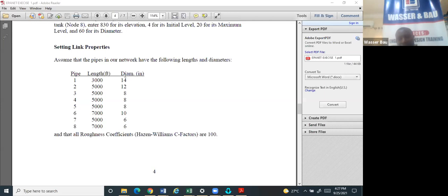All these things have to be designed anyway, depending on how many hours you are pumping and the capacity of the pump: the head and the discharge. Every pump is defined by 2 things, the head and the discharge. The higher the head, the lower the discharge. The lower the head, the higher the discharge. So you should be able to look at what you have in your network and know which one you have more, and make sure that those 2 are all met.